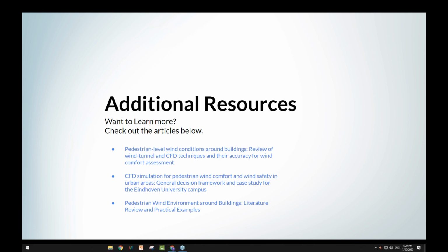There's another question actually. Can I get force results on buildings? This is something I haven't shown you, but we can use LBM simulation to also output force plots on building facades. So you can monitor the pressure forces on particular locations. You can select the face before you start the run, and it will compute an average force on the specific face.